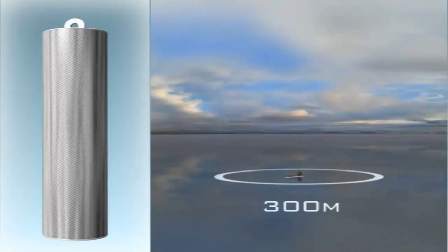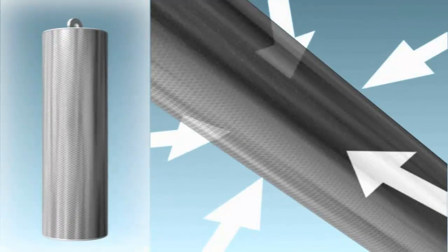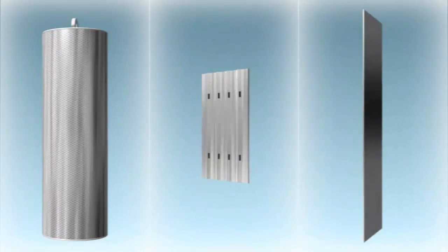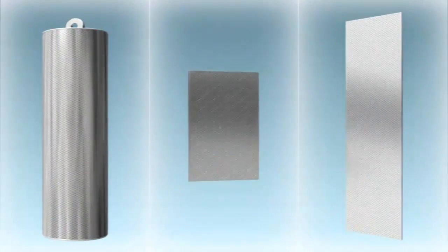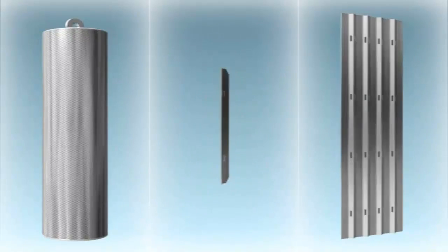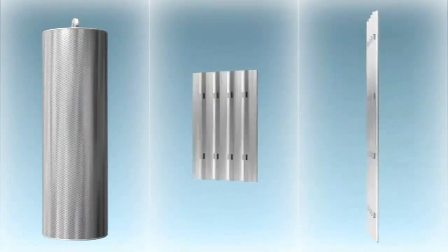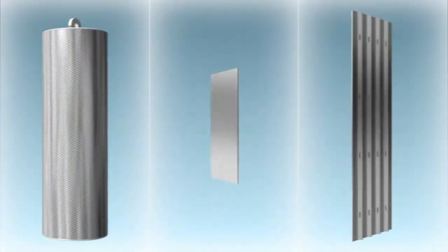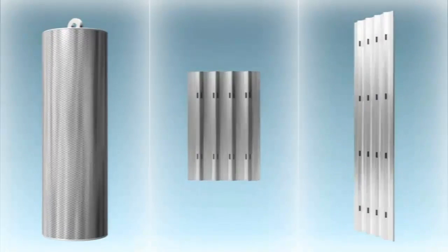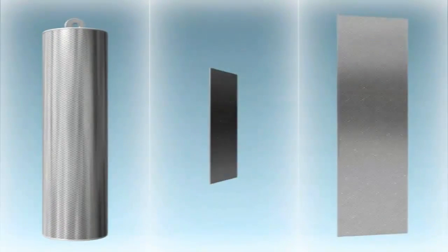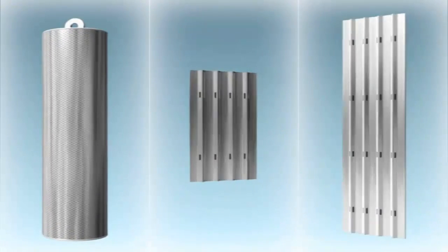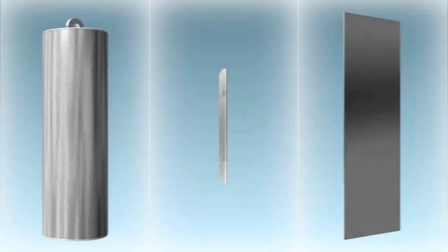For the greatest flexibility, and for ranges up to about 300 meters, 1.5-meter-high cylindrical targets are best. These can be seen by Cyscan from all angles, and so do not restrict the vessel approach angle. Targets can be supplied by your Cyscan agent or direct from guidance in the UK. You can also construct your own targets. However, it's very important to use 3M Diamond Grade White 3970 for the best results. Other reflective materials will downgrade Cyscan's performance. See the technical notes in the operator's guide for full details.